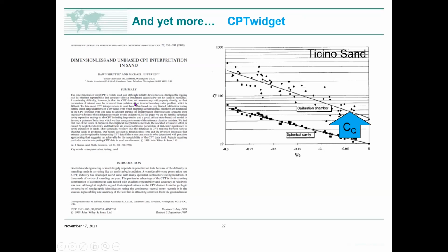So it's very easy to do a large deformation analysis, and you have to do large strain because if you don't, you won't get a cavity limit pressure. You have to worry about things like advected, because when you move a mesh, there's loads on the mesh. You've got to deal with advected stresses and advected work.